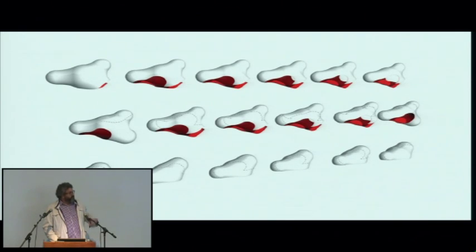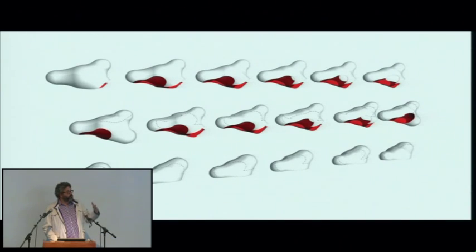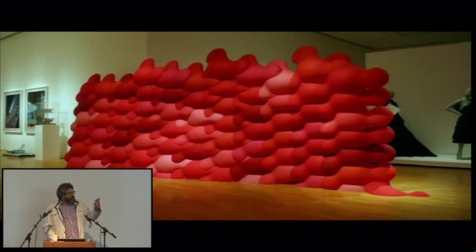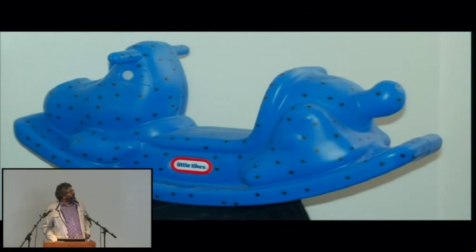But we, with Panelite, a company in Los Angeles, came up with this freestanding wall system where we take a modular brick that I designed that has these kind of 3 nodes, and we digitally array those instead of, let's say, in a geometric primitive or form. They're arrayed along animation paths, and we find the intersections of each one of these elements one to another, and then cut them with the robot, and then fit them together in a non-modular way. So it's a modular system of construction, just like a brick, but instead of mortar, the variation is cut with the robot, and then they get bonded, melted together into a monolithic object. And we've done a bunch of these as walls. We did one as a giant brick, where it became kind of a self-supporting dome.